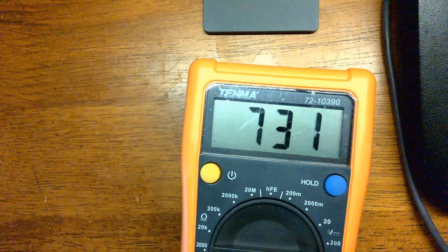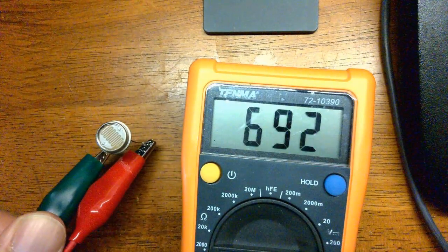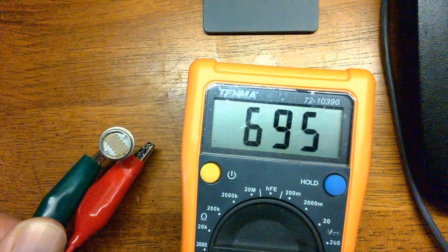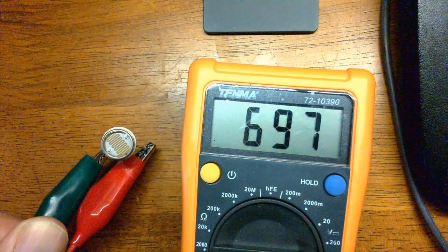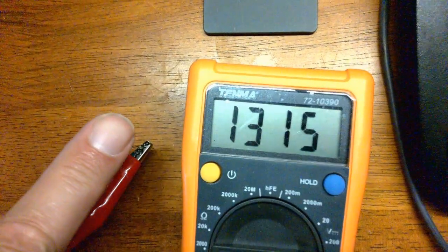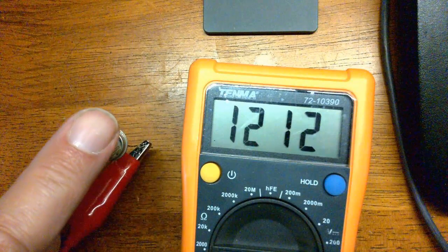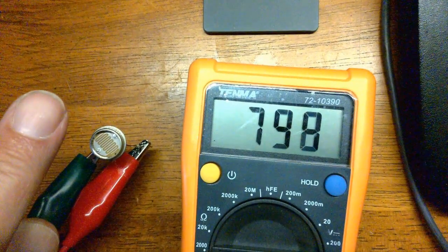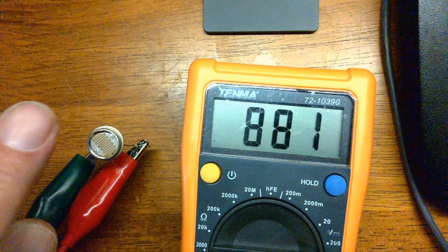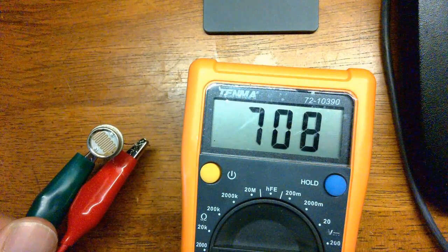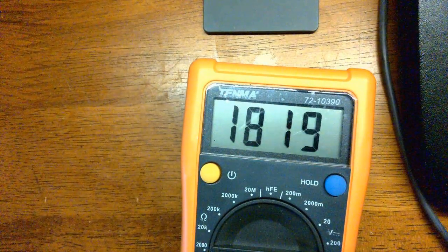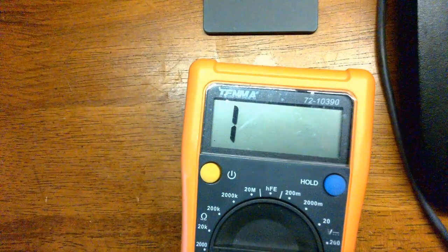Here's another type of semiconductor. So this is a cadmium sulfide, or CDS, light sensor. When I hit it with light, I have a low resistance. As I put a shadow over it, the resistance goes up. So photons reduce the resistance. Again, why is that? Why is it that for semiconductors, heat or light reduces the resistance, whereas for metals, the resistance goes up as temperature goes up?